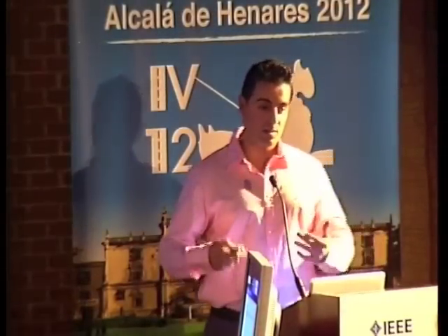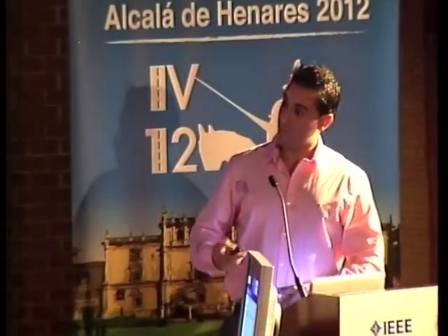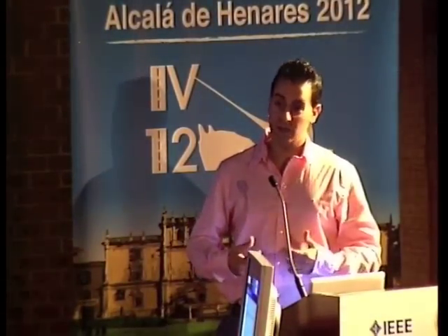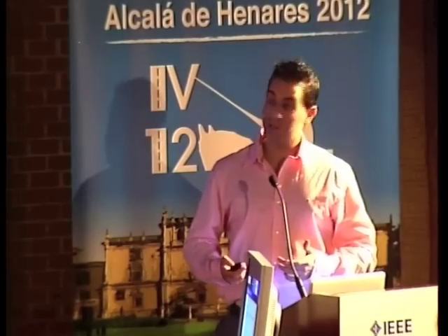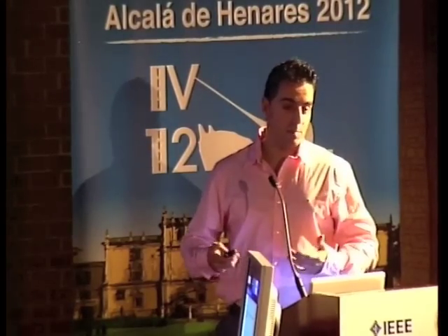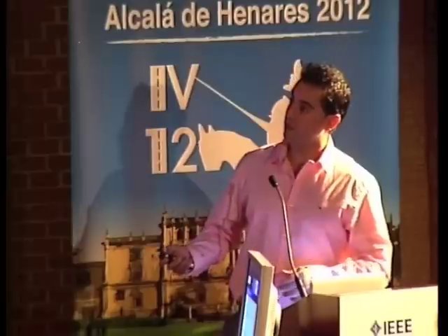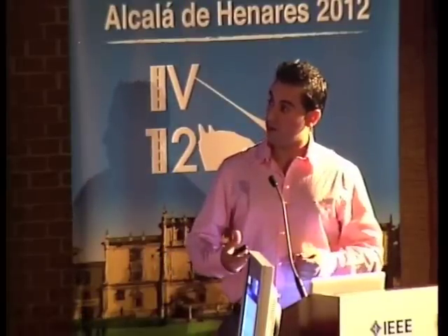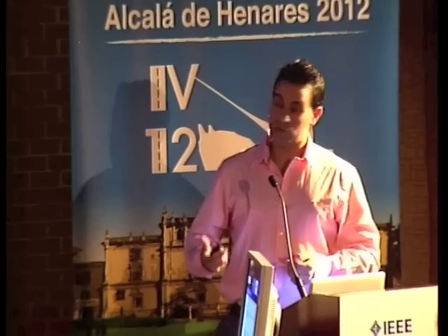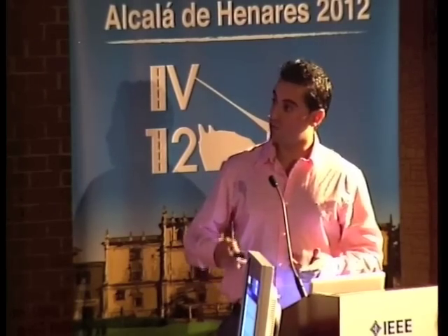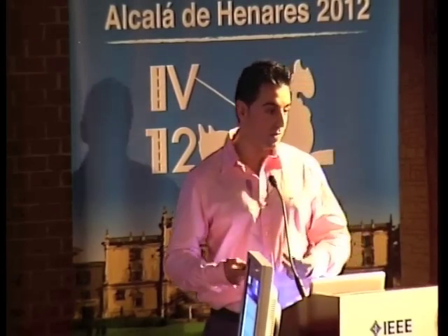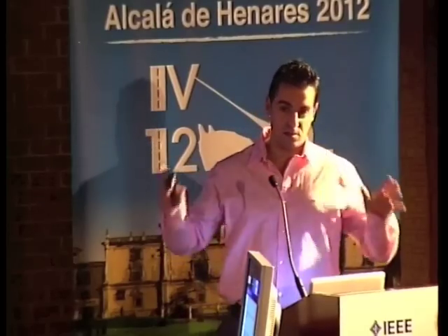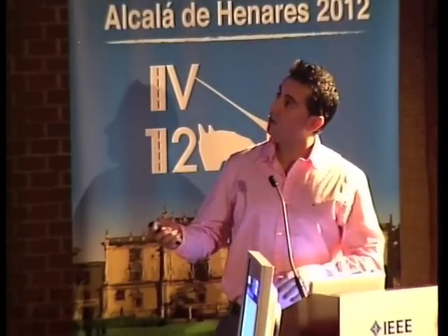Well, then, in our proposed method, what we have to do now is to find a finite number of noise sources that are uncorrelated and are producing the most part of the energy inside the car. So first of all, we have to define a measure of the source correlation, and after that we have to make a search algorithm in order to find the position of the sources along the contour of the car.